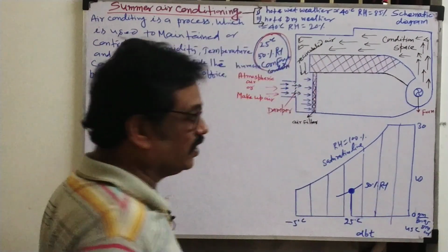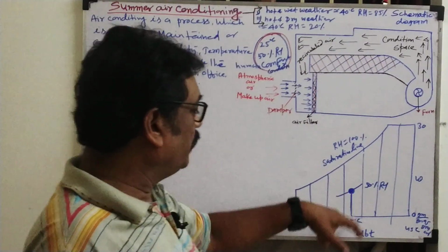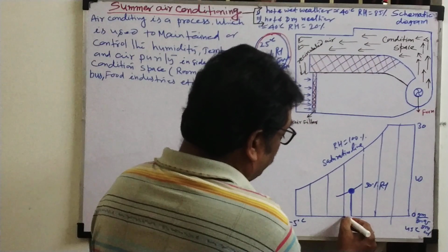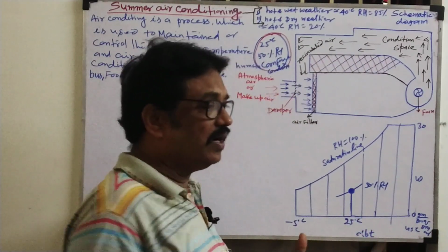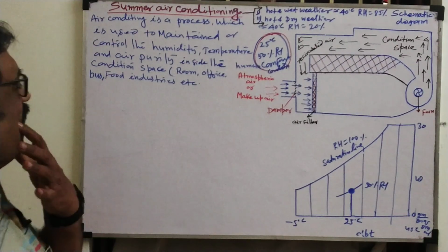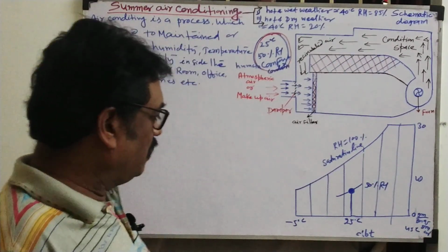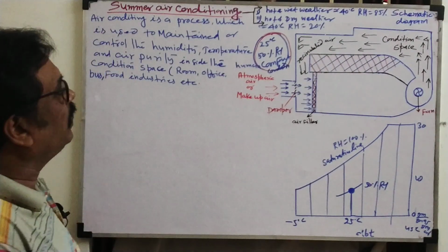In any psychrometric chart, in the middle you will see one circle. That circle means the human comfort condition. In these conditions, human beings will feel comfort, without fan, without AC. Now how to design? We have the psychrometric processes, and with the psychrometric processes only we will design.